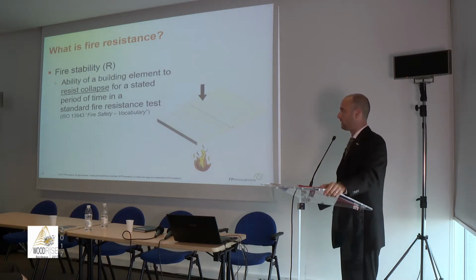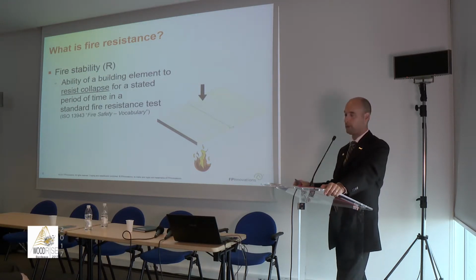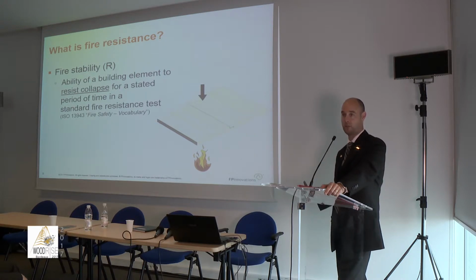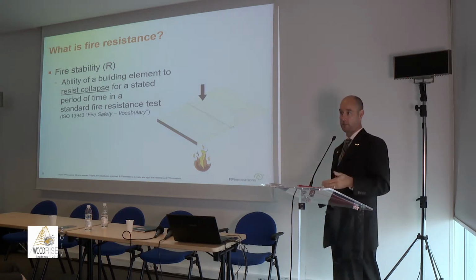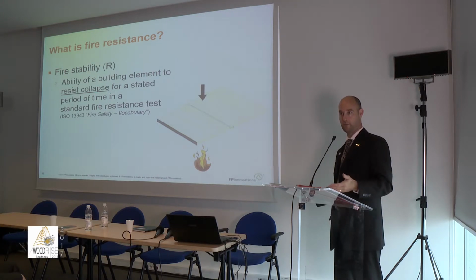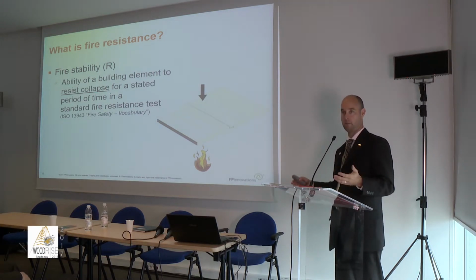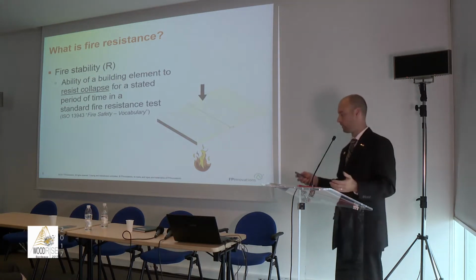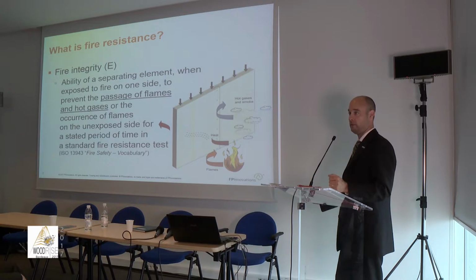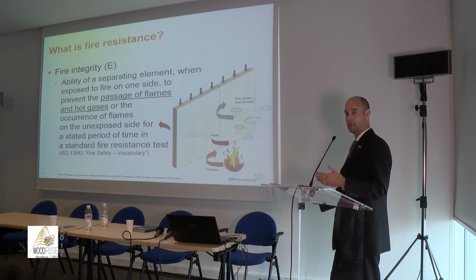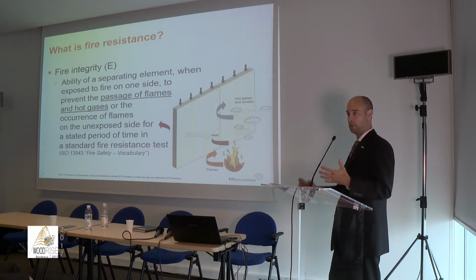So there are essentially 3 criteria, and I apologize, Koji already showed similar slides, but fire resistance has 3 criteria that it needs to meet. You have the load-bearing capacity. It has to be able to withstand the applied load for whatever duration. In the case of tall buildings, it would be between 90 minutes and 2 hours. You also have the fire integrity, so it has to limit the passage of flames and smoke through the assembly. That can be any compartment boundary, so it could be walls or floors, or again, it could be doors.